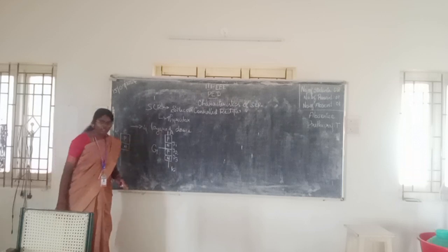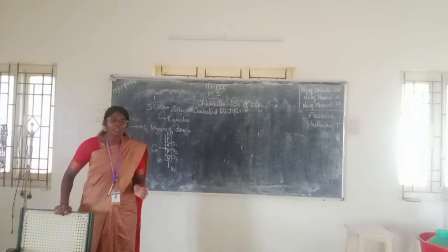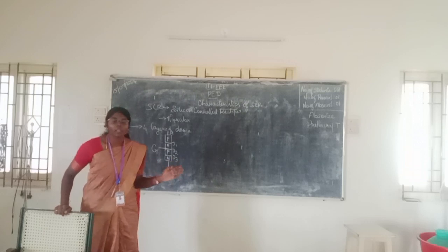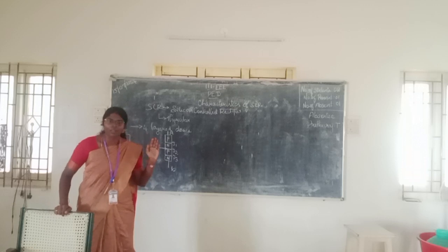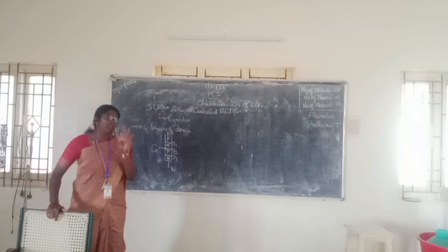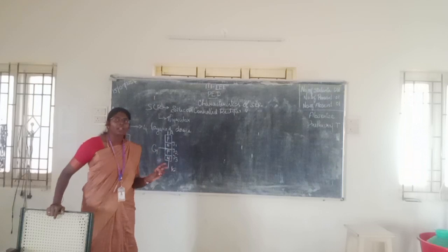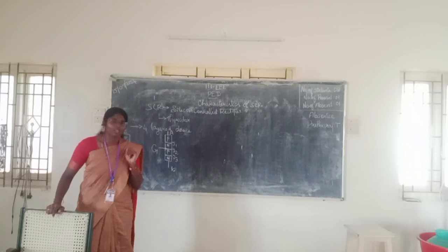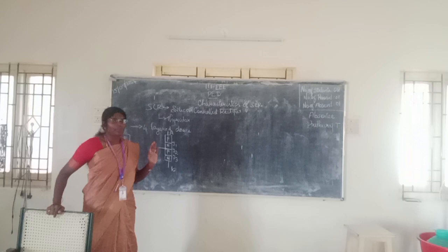So the silicon controlled rectifier is a semiconductor switching device. I told in the last class that it is used to control electronic operations, in switching on or off and in controlling rectifier circuits. So we are seeing SCR, later called thyristor, having 4 layers: P type semiconductor, again N type, again P type and again N type, having 3 junctions J1, J2, J3 and 3 terminals, anode, cathode, along with that the gate.